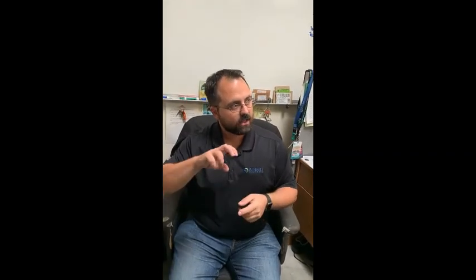Right, okay. And all the programming is in the controller, not really the sensor. The sensor just takes a reading and the knob values and sends them back and forth, but there's no programming in that part. The controller's another story. It's programmed, probably, if one goes out or something. And with LON, it's kind of tricky to replace a controller versus BACnet.